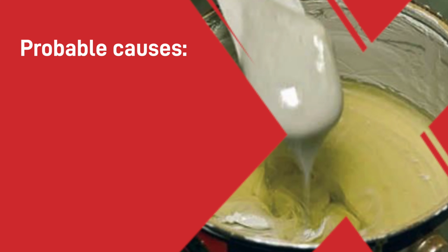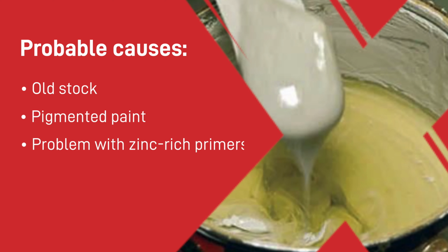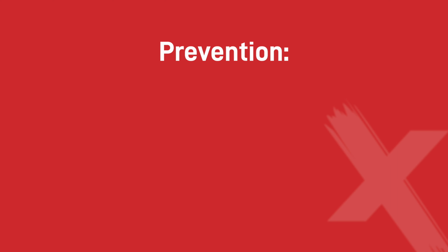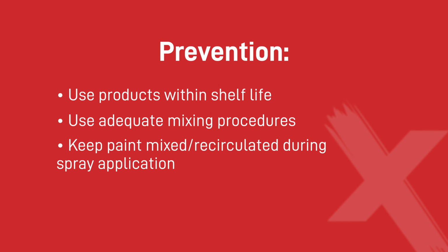This is a very easily avoidable fault, as the most likely cause is a lack of correct mixing at the formulation stage. Always ensure adequate mixing with a paint mixer to get best results. There are also other possible causes such as old stock or heavily pigmented paint, as found with zinc-rich primers. To prevent this, use products within shelf life. Use adequate mixing procedures and keep paint mixed or recirculated during spray application.